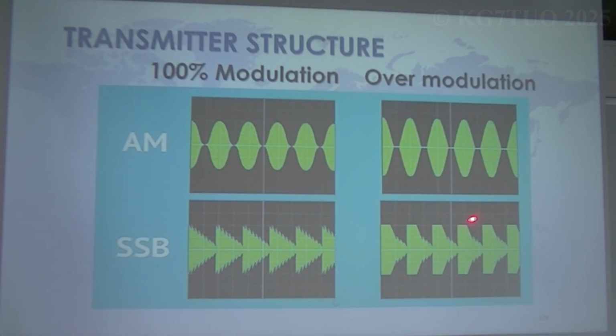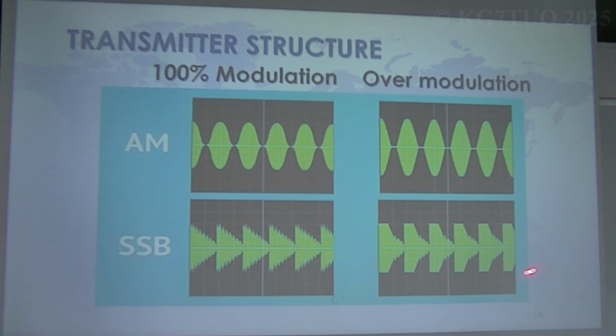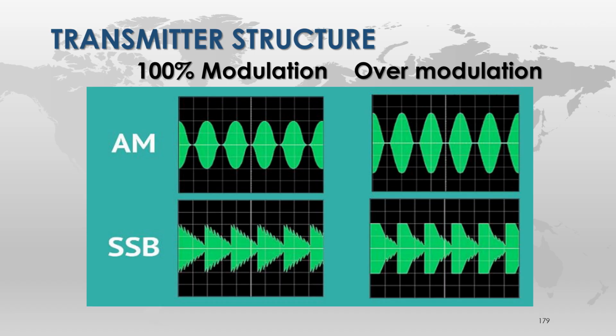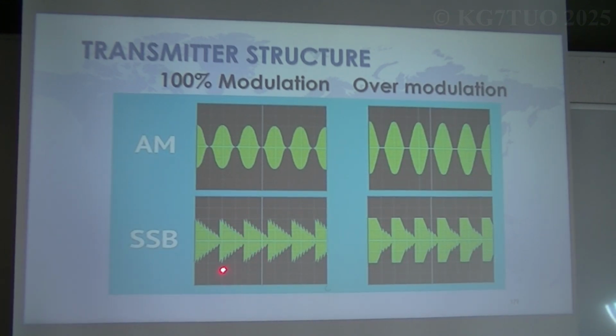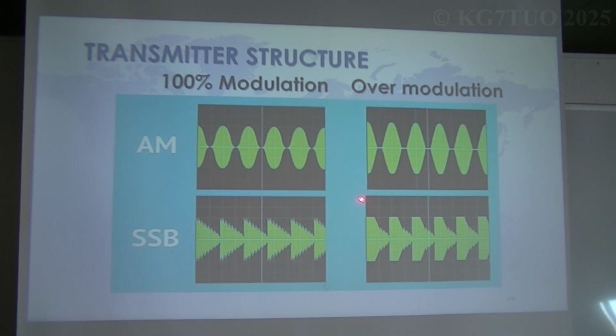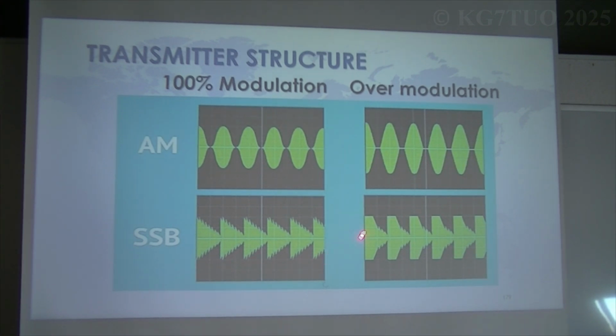You see that clipping up there? You are losing part of your audio, and that comes out. This looks an awful lot like a CW waveform to me. So when you talk about clipping, you see the nice triangle there, and then this one's got a flat top. Well, that's because this triangle was way up there, and now it's been just chopped off. And what you have done here is you have caused your transmitter tubes or transistors to stop doing gain. You're topping out that transmitter.